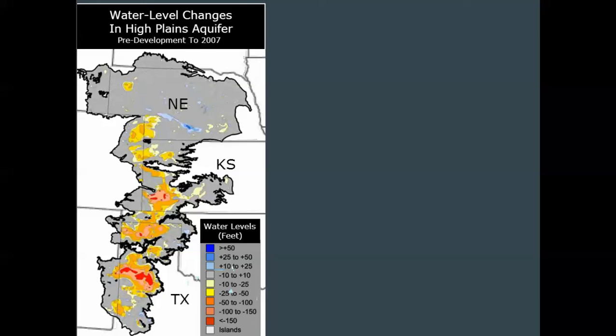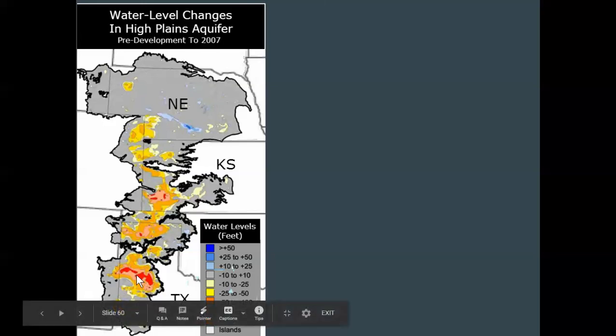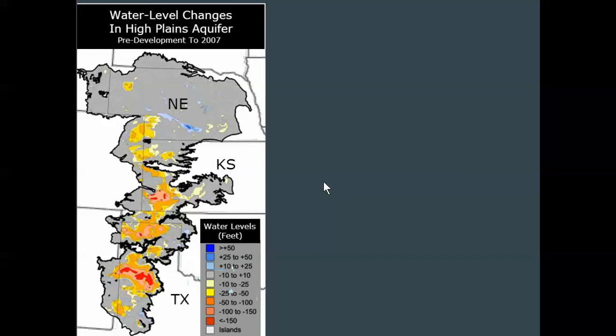And in some areas, especially in North Texas and in South Kansas, we've seen drawdowns in excess of 100 feet. And that's a massive impact. If we think about this as literally mining water out of these aquifers, and the discharge, while very rapid, the recharge, that is the additions to water, this can be thousands of years. And so here we're pulling water much faster than it goes back into the system.